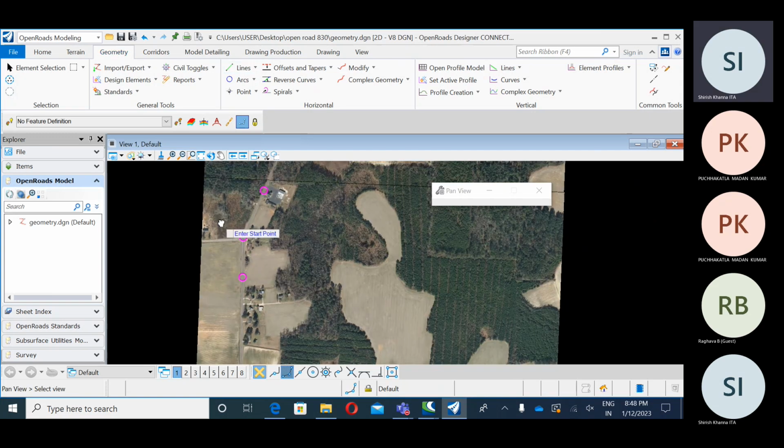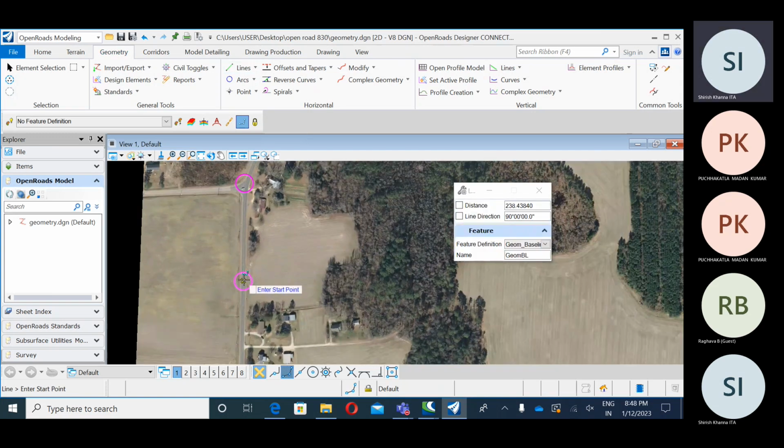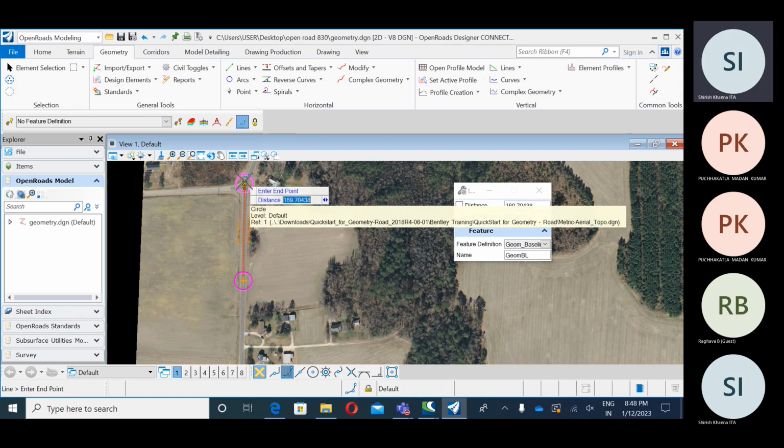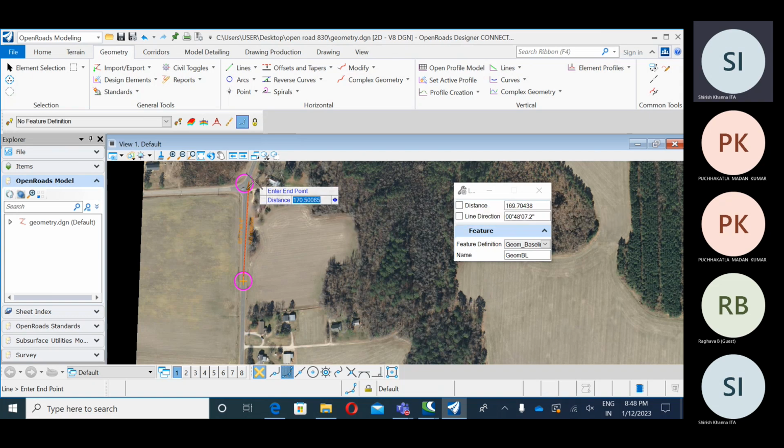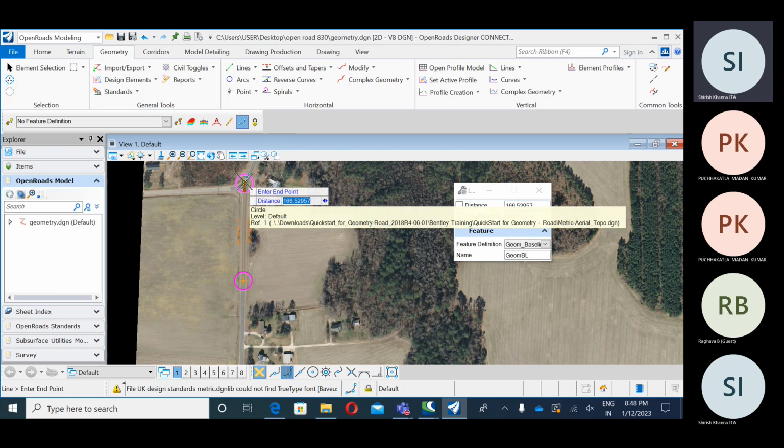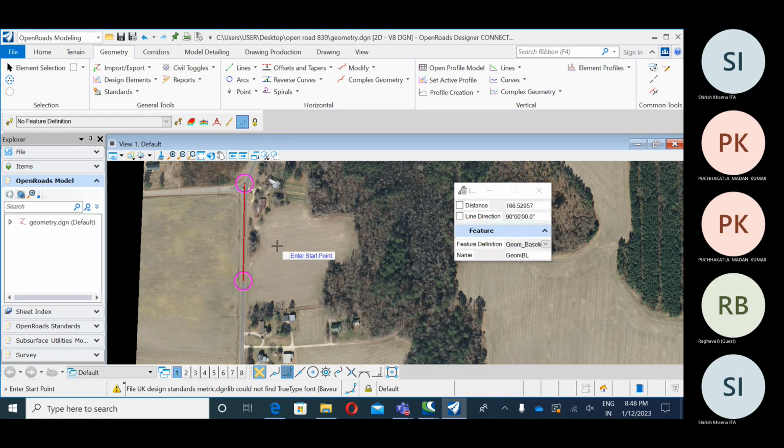From the first point, the center is not picked by default, so go for the snapping, and then you can choose the first point and second. If you have data, I told you yesterday how to give a distance and angle. First it's setting the distance. Left click to accept. Then it's asking for the angle.